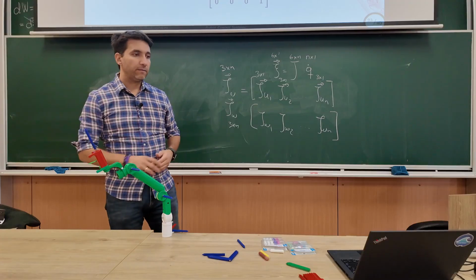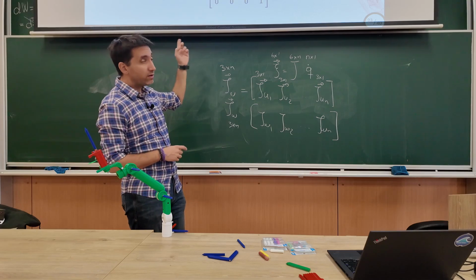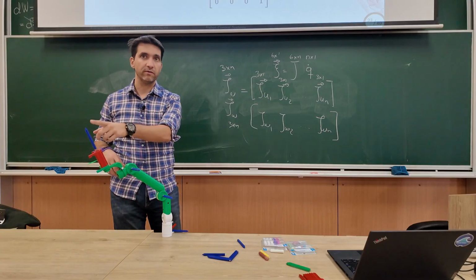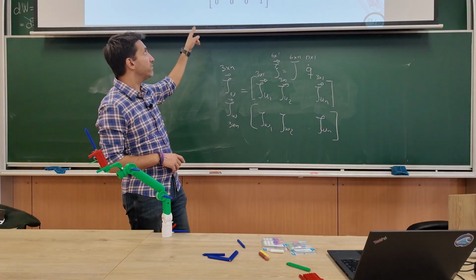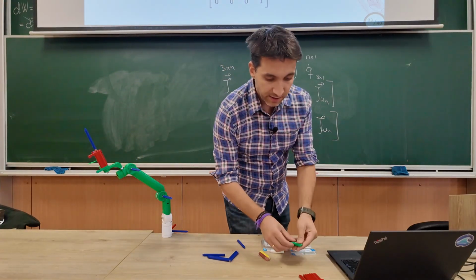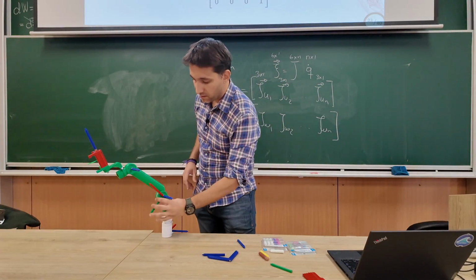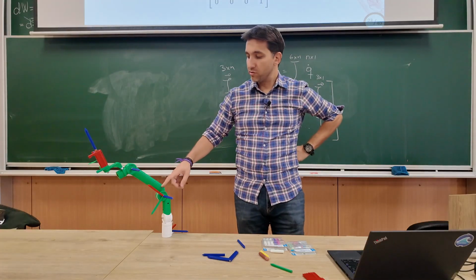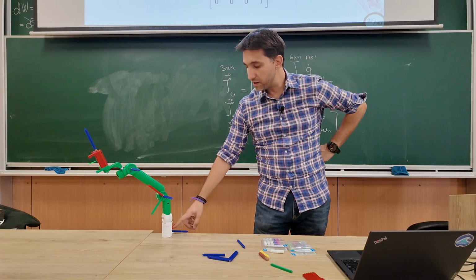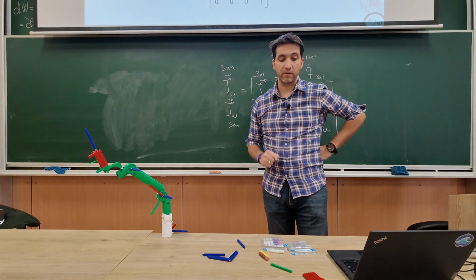And then we can take that z by calculating the transformation using the Denavit-Hartenberg convention from the base frame until that joint, right? If I do that, I will have the transformation matrix that represents, let's say for joint 2, something like this. I will have the transformation matrix describing the position and orientation of frame 2 with respect to the reference frame, given by this 4x4 matrix, right?